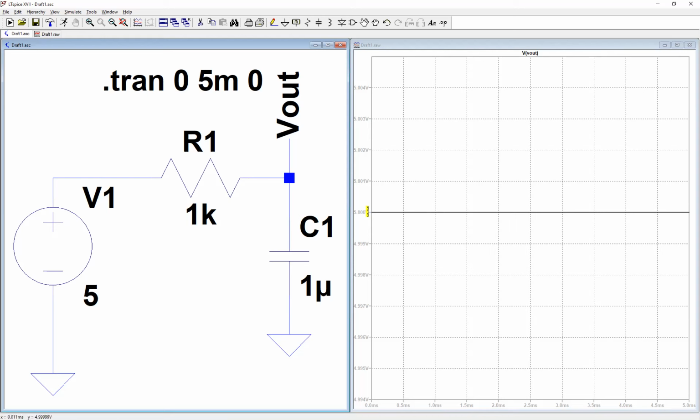Remember, at 0, I repeat it again, at 0, LTspice substitutes the capacitance with an open circuit and the inductance with a short circuit. After that, it starts to run the simulation. So at 0, if I substitute this with an open circuit, the voltage here is 5 volt, as I explained before, and then it starts to run the simulation, but the capacitance is already charged at 5 volts, so it remains always 5. So this is the problem.